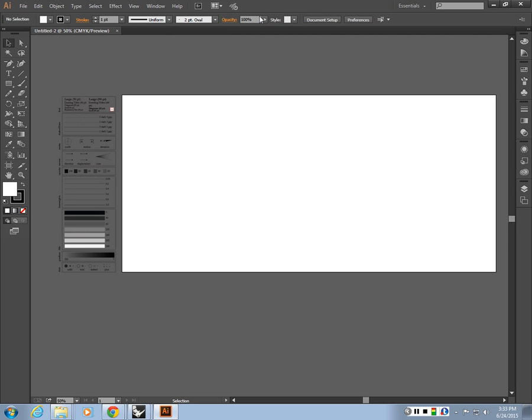Illustrator is mostly used for vector based graphics, so we could assign line weights, shades, styling, filling to graphic objects basically, and this is where we would do the line weight adjustment for our drawings, right? So we will prepare an abstract file with different layers, and we will bring it here and assign different line weights or line types to different layers in Illustrator, and that's something we cannot do in Rhino.